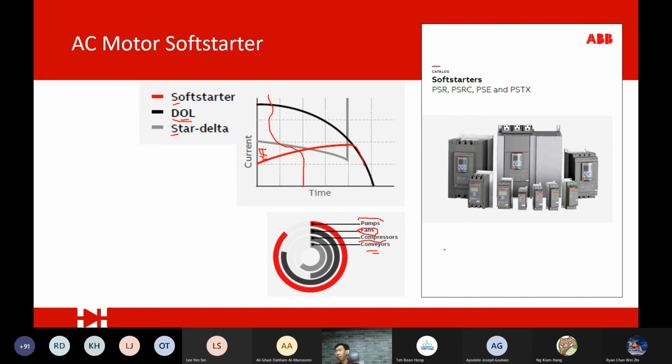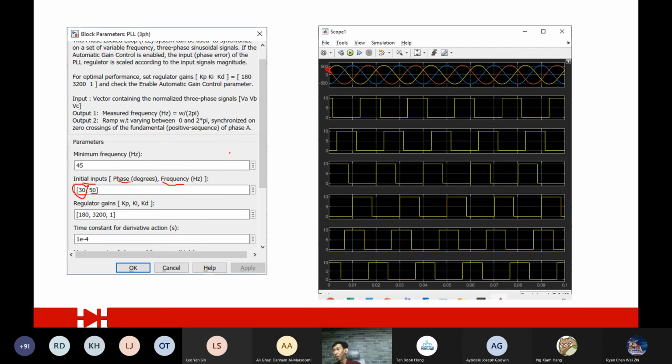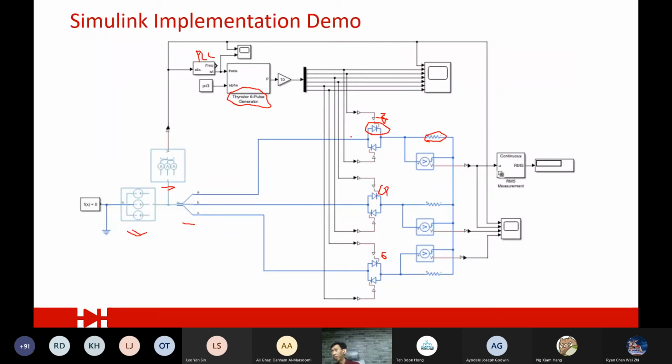The real solution is that you put a soft starter on every conveyor. They start at the same time, it won't trip, it gives a soft start. Meaning that it starts at the lowest voltage, and in other words, you won't use this to operate a motor for like 1 hour in this waveform. No, it's for soft starting purposes. So don't get me wrong, this is for three-phase application. Single phase, you can use it to turn on your LED light 24 hours, no problem. So different application.